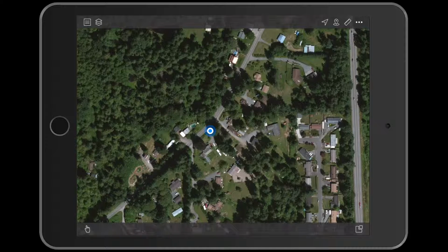If you draw for anything more than a temporary purpose, think of drawing as creating a new feature in a shapefile. All such data that you create on your phone or pad with Apex is saved in a local layer. A local layer is the onboard version of a server layer. You may upload local layers to the server, where they become server layers and may be shared as common shapefile formats. Apex provides full control of your local layers, including creation and editing of a local layer's feature data fields and data. See the Apex Basics Local Layers and Apex Advanced Local Layers videos for more information.